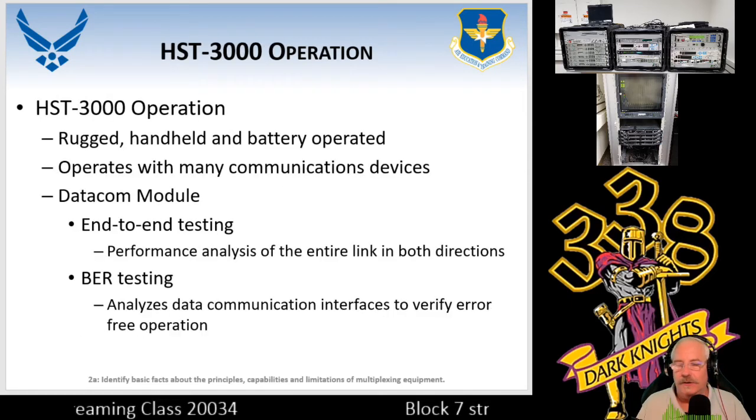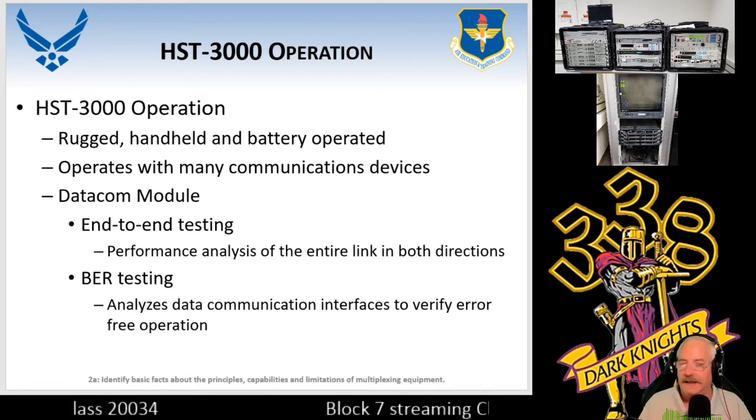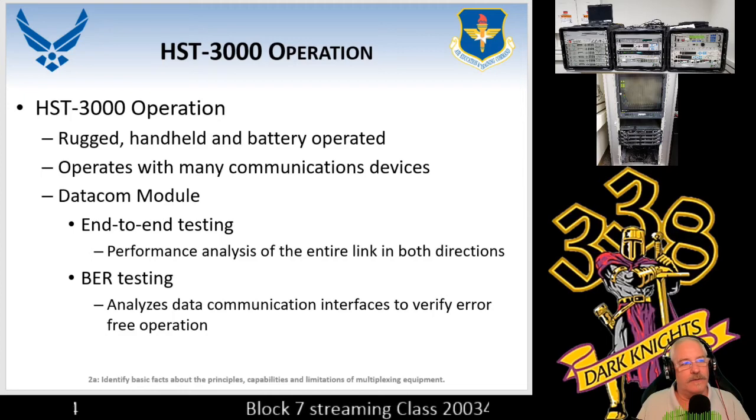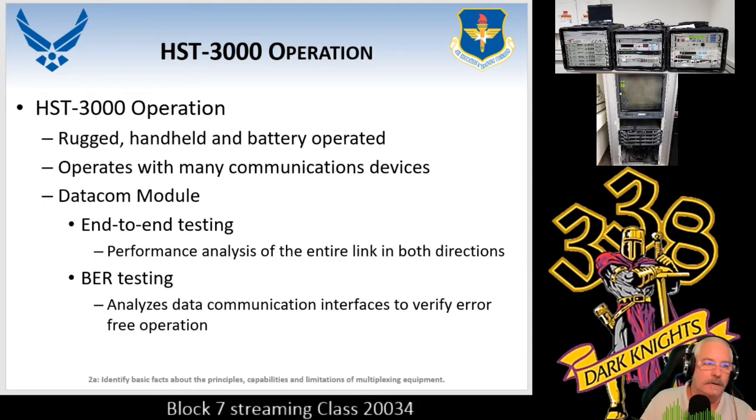Now, the BERT that you guys are going to be using is called the HST 3000. This is considered a datacom module. So if you see anything that relates to the datacom, you need to reference everything to the HST 3000. You can see it does end-to-end testing, the bit error rate test.